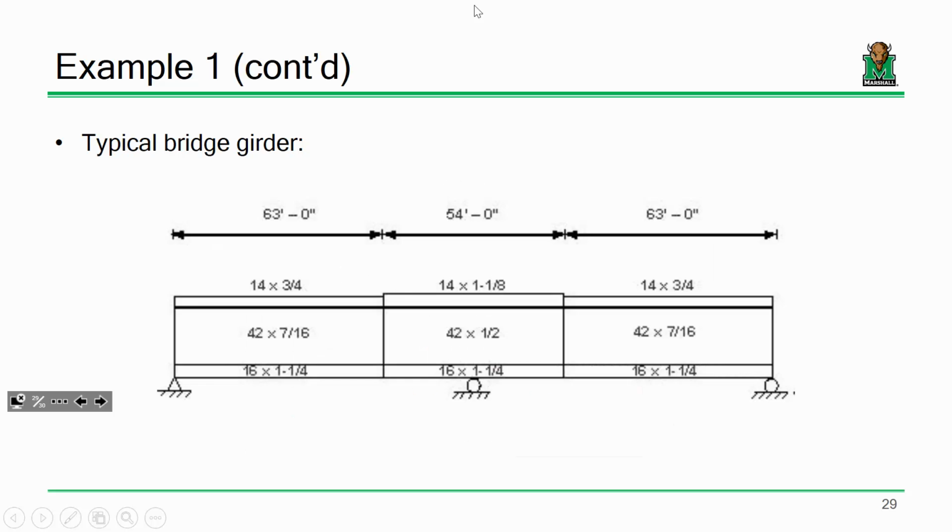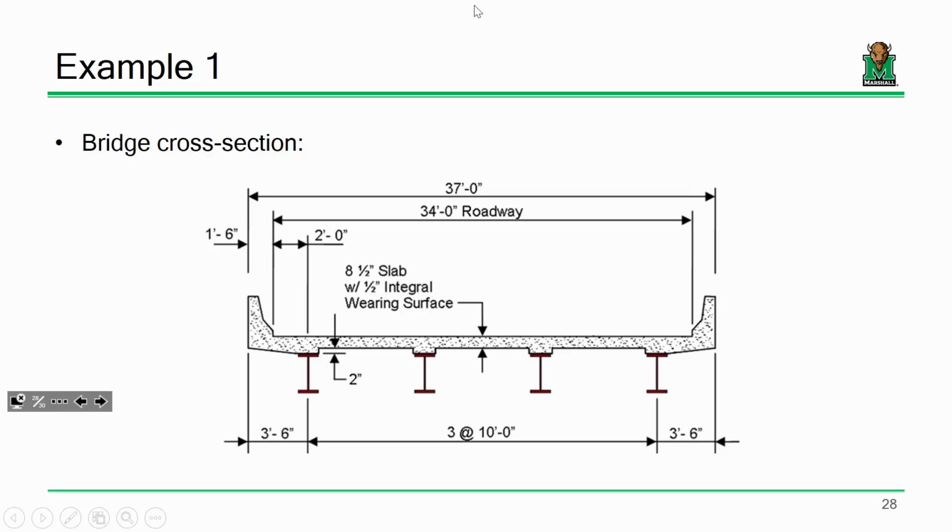All right, so we looked at this structure and we went through and discussed how to compute non-composite section properties and then composite ones. And what we found was it really doesn't matter. Once you've gotten the composite section properties down pat, they're all the same really. I mean, what's the difference between short term and long term? It's just a different n value. Instead of n, it's 3n.